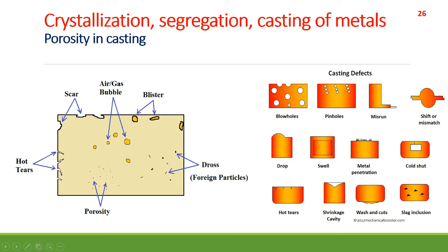Here you see blowholes. Blowholes are gas porosity, but they are larger in size, so they are called blowholes. Here you see pinholes. They are smaller in size.